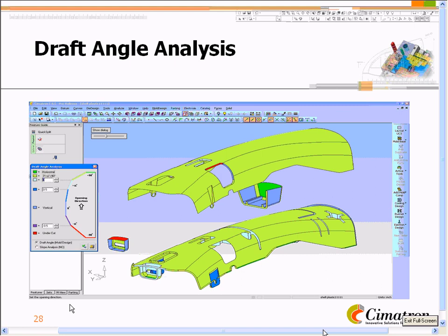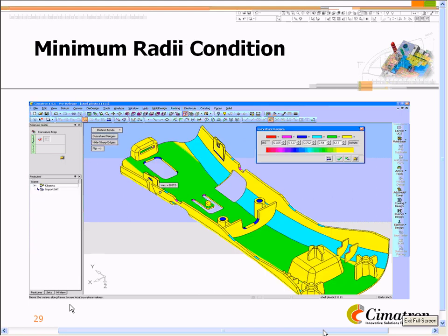Going a little further with this, there being actions involved inside the part itself, here you see a lifter and a slide condition. It's good to know if you can actually pull that out in the correct position. If you look at the lower left, you see the red sitting on that little slide. Based upon the way it was designed, that area would be undercut on that slide.